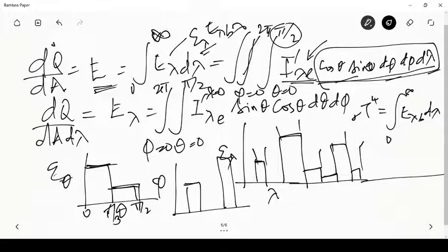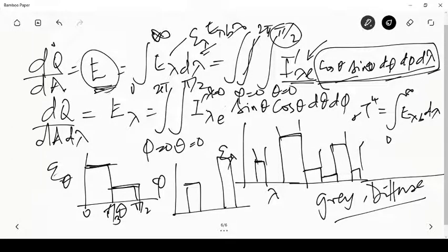So for a first course of thermodynamics, or even at undergraduate level, typically the assumption that is commonly invoked is gray diffuse, saying that we will ignore spectral variation, and we will ignore the directional variation of any emission, so that we can just treat this as a single quantity for the entire hemisphere, okay, and for the entire spectrum. So that is the thing that is commonly done.